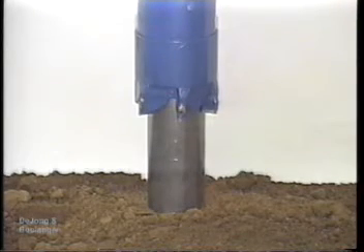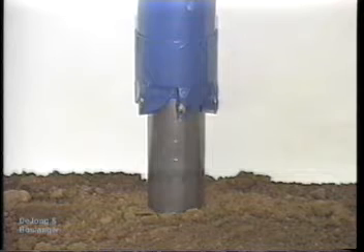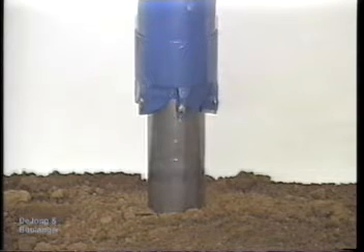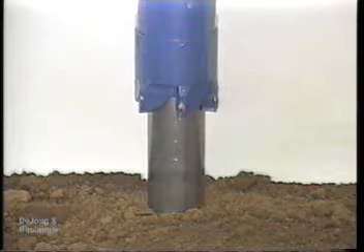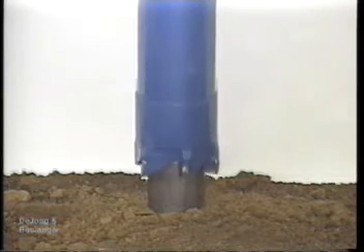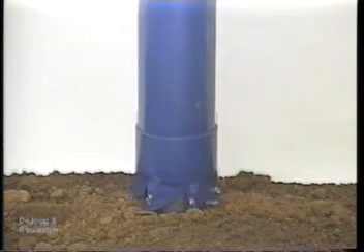If the soil is hard, the spring is compressed until the cutting edge of the tube is forced above the bottom of the cutter barrel. As the barrel rotates, it cuts an annular ring, leaving a cylinder of soil over which the sample tube slides. The tube thus protects the sample against erosion by the circulating fluid. In this manner, the pitcher sampler adapts itself to the stiffness of the soil.